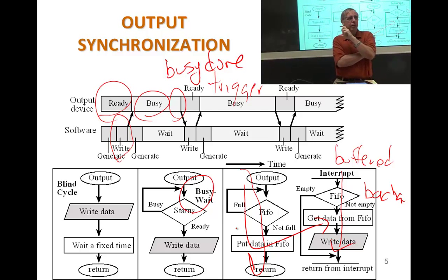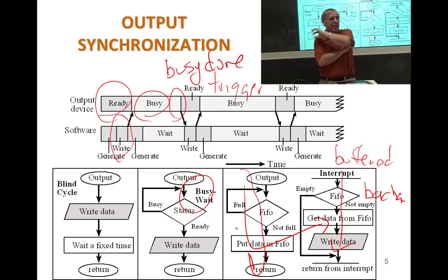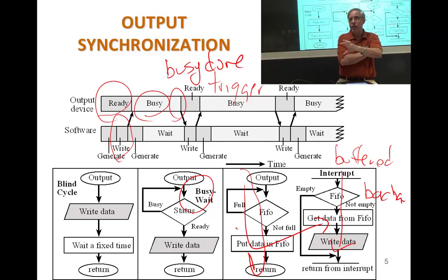Where you can look at the values of variables. You can put variables in your Watch window, okay? And then you could set it up to periodically update, and you can look at your variables as your program's running. Now, it's a little bit intrusive because it has to go fetch that out of RAM, but we saw it sneaks in the backside, by the way. Doesn't go through the system bus. Sneaks in the backside to get it out of RAM, so it slows it down just a little bit.